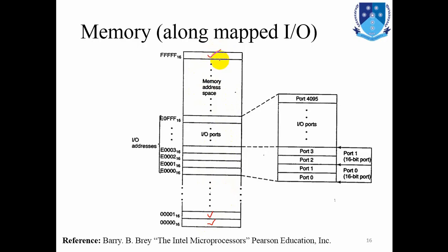These locations are equal in size. Each location has a unique address in order to distinguish it from the other locations. Here you can say that the starting address of the very first location is 20 bits of binary, which can be represented by 5 digits in hexadecimal. Actually, that is a 20-bit binary number.